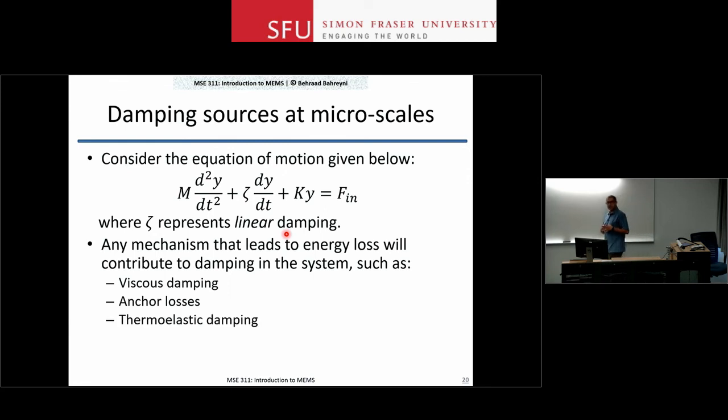Another one is thermoelastic damping. Again, this is happening in vibrating structures. You probably have seen this so far. If you take a plastic ruler and somehow fix one end of it to something and try to bend it up and down many, many times, repeatedly, after a while, if you touch where you were bending, you will notice that the temperature has risen, right? The mechanical energy that you used here to produce strains and stresses, a little bit of it has converted into heat. Once it converts to heat, it's gone. It's lost. So thermoelastic damping is that source of damping.